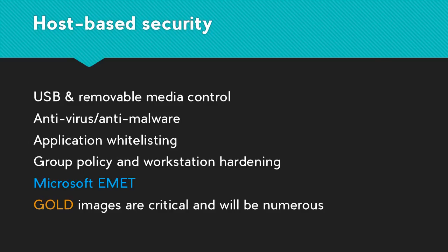Whether that's whitelisting a brand of USB scanner. There's tools out there. Norman, I think, was bought by Symantec, but it was the Norman Shark product. It actually has an agent that sits on every workstation. You have a wall-mounted PC with a whole bunch of USB ports on it, and you plug your USB key or drive into the panel. It scans it, writes a signature against the entire disk, and then you take it out and plug it into your engineering workstation. The Norman agent validates the signature hasn't been modified, and then it allows you to run from it.